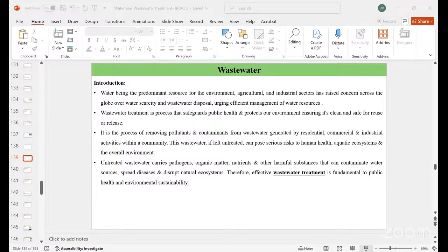The biological treatment relies on the metabolic activities of a diverse community of microorganisms. These microscopic organisms, primarily bacteria, but also including fungi and microalgae, act as natural bioreactors. They consume the organic pollutants present in the water as a food source, converting them into energy and new biomass through oxidation processes, and the microorganisms obtain the energy necessary for growth and maintenance.